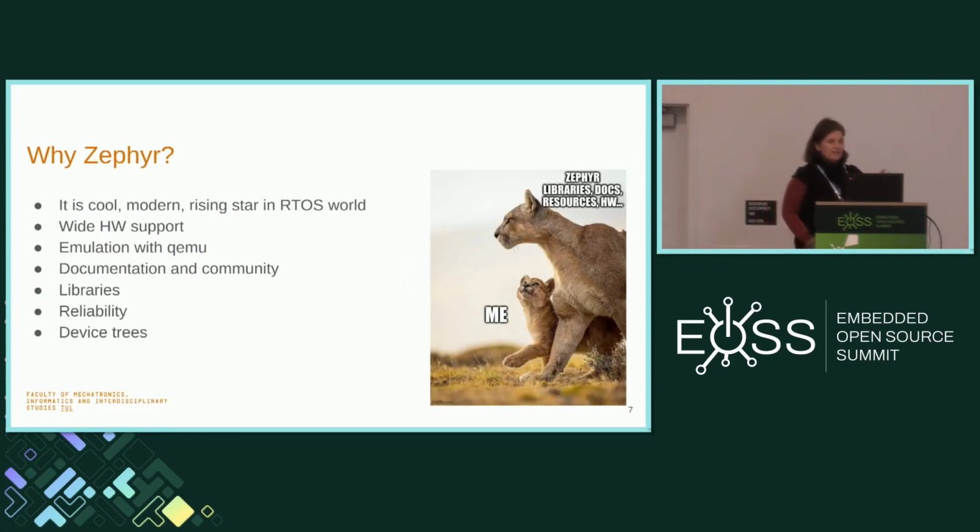Mostly, from my point of view, what I really like here is that Zephyr supports several architectures. In one lab you can say, we've explained that you have several layers in the operating system, and you need to be portable to different platforms. So within one lab, we are booting the x86 platform in QEMU, and then we are booting some ARM-based board, changing just one configuration option to demonstrate that it's working.